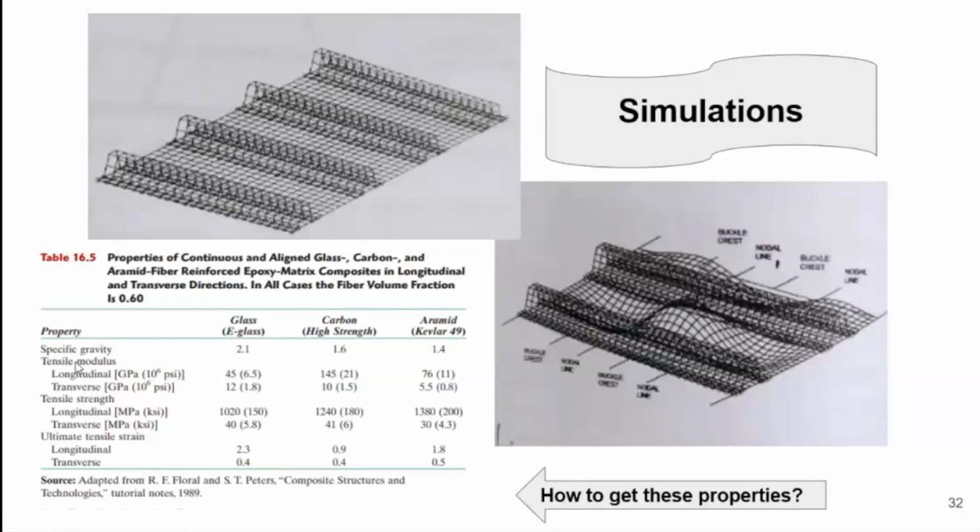This is anisotropic material, because there is a transverse property. For isotropic, we only have tensile modulus, only one number. However, for this composite, you have to have the property with respect to their fiber direction. So that is a big problem. That's why for the case of Eagle, we just end up testing everything rather than coming out with the properties and then doing the design analysis.